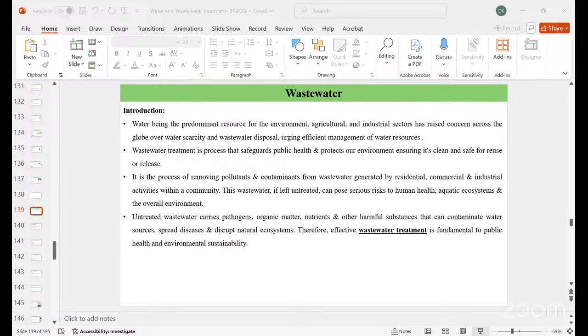Sludge removal can be done mainly by mechanical scrapers, in both rectangular and circular tanks, to move the sludge into a collection point. Coming to hydraulic removal, pumps or gravity are mainly used to remove the sludge. The detention time is based upon the time water spends in the tank, and it is crucial for effective settling. It is calculated based on the water flow and the tank volume, and adequate detention time is necessary for the particles to have sufficient time to settle.